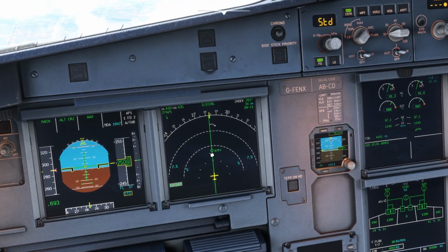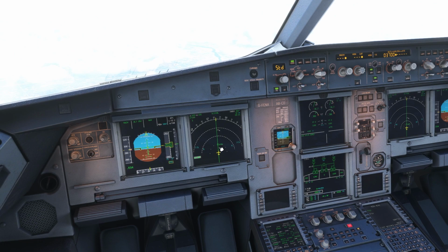This is the ETP, as I was telling you before. If you want to go back to Lahore, this is a good point. Otherwise, after crossing this point, it is better to land at Islamabad than going back, or to choose any other airport over here. So this is a good indication also over here.